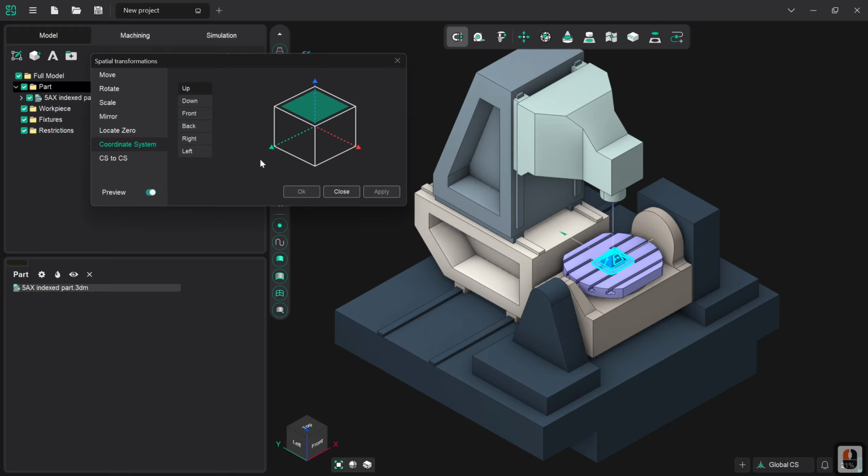Beyond this, we can also define what the coordinate system orientation is going to be for your actual part. So if we pan through this, you can see how the part moves in accordance with that, and that's in conformance with the world coordinate system. So the part is reoriented according to what you define as its coordinate system relative to the world coordinate system.